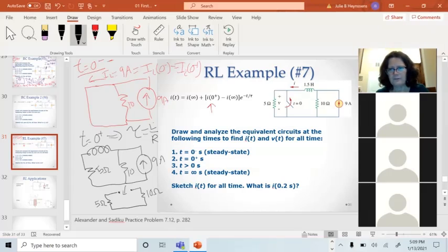The way I figure this out is I say, I'm an electron and I'm moving through the circuit. If I'm going through the 5 ohm and I have to go through the 10 ohm to return, they're in series. If I have a choice of going through the 5 ohm or 10 ohm, they're in parallel. So in this case, they're in series, so I can just add them together. So my REQ is 15 ohms.